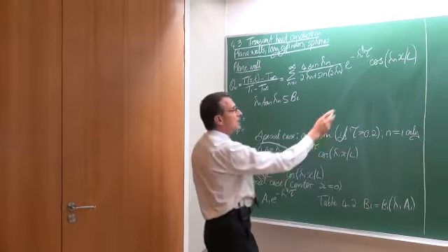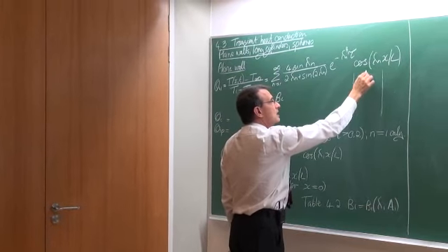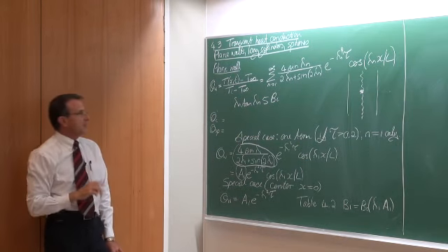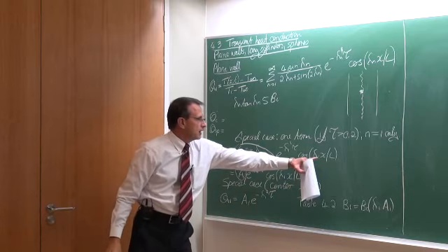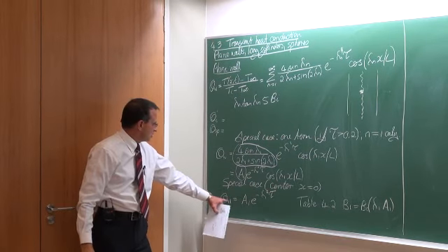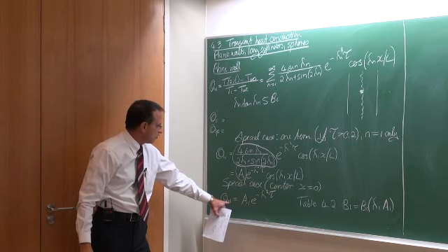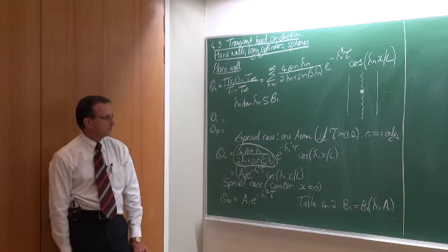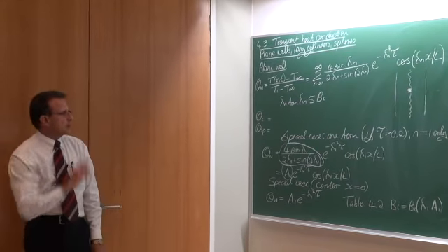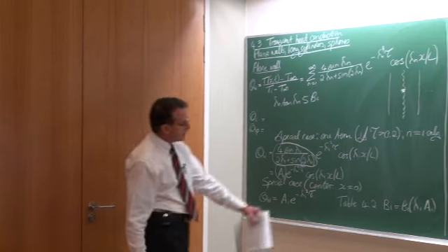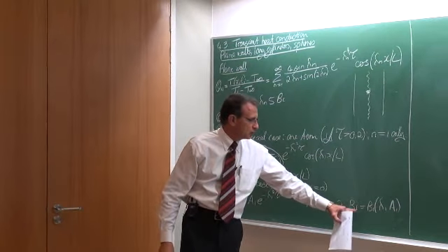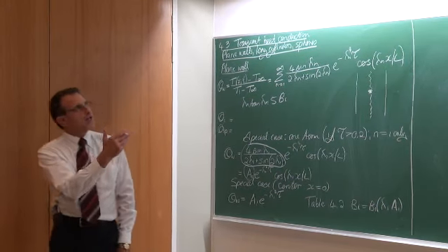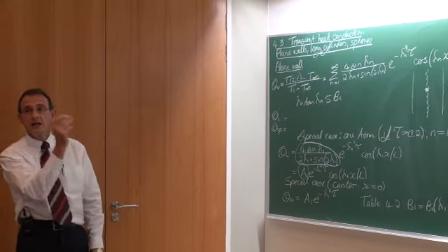Okay. Now for this, another special case is if we are interested in the solution where x is equal to 0. Now if we look at the plane wall, then it would be here on the mid-plane. So if we want the solution in the center, there x is equal to 0, and if we put it into that equation, the result is that the non-dimensionalized temperature at the center of a wall is equal to A1 e to the minus lambda 1 squared multiplied by tau. And the authors were so kind to, in table 4.2, give us the Biot number as a function of lambda and A1 for the 3 different cases of a plane wall, a cylinder and a sphere.